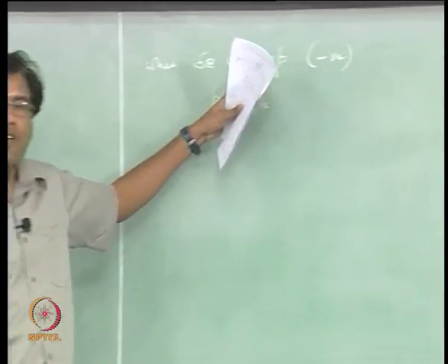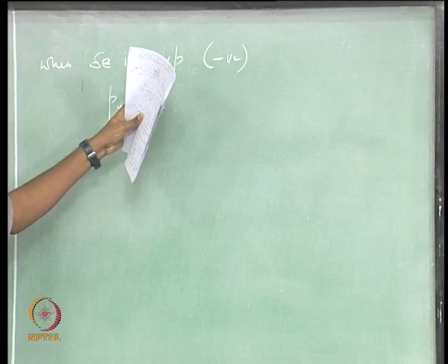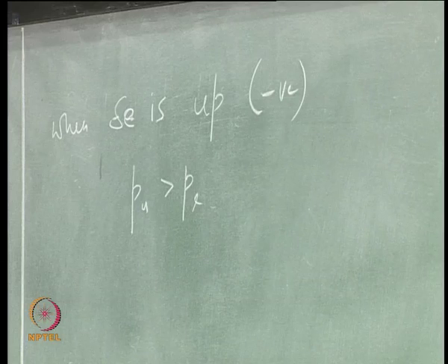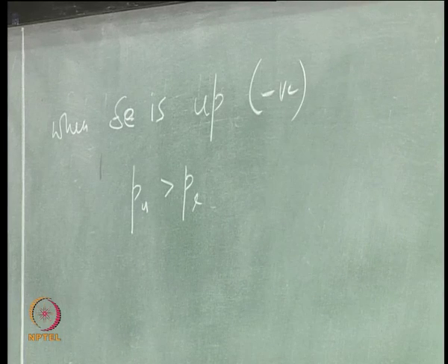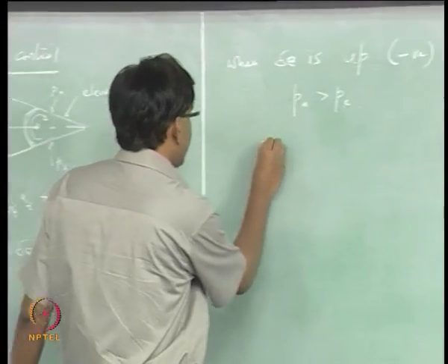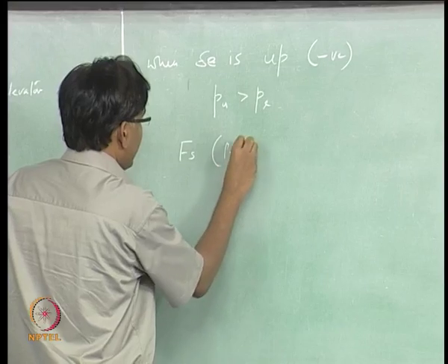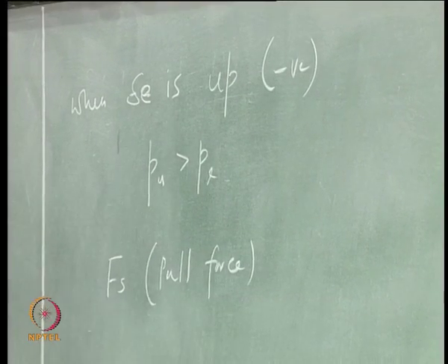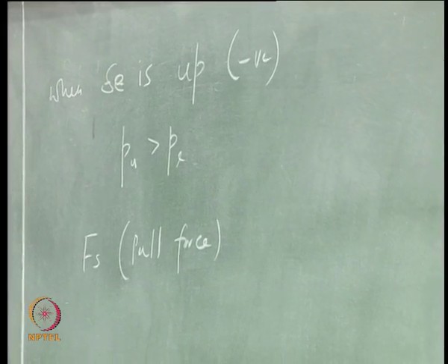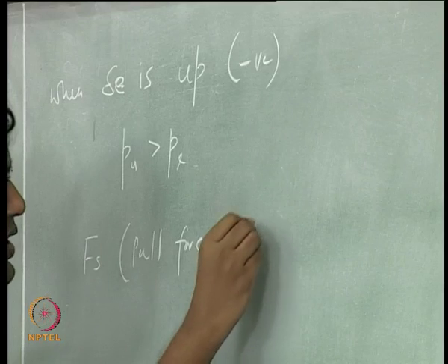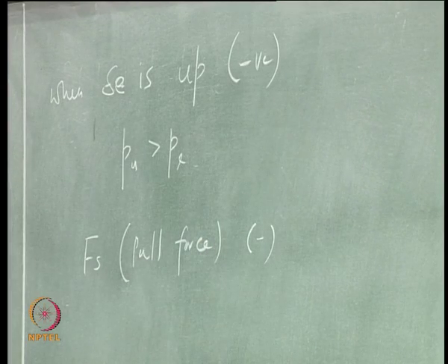So what should be the stick force? I am deflecting the elevator up, right. So yesterday you saw that the mechanical arrangement was such that I have to pull Fs, or the stick, towards myself, okay, to deflect the elevator up, and that is Fs, right. And the convention is that this pull they use as a negative stick force.